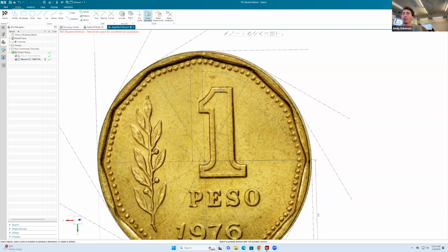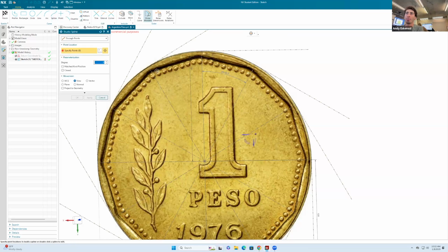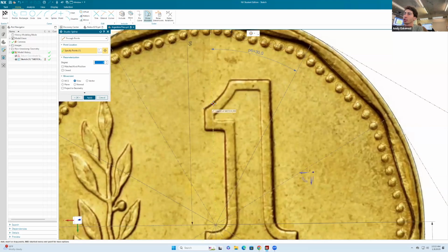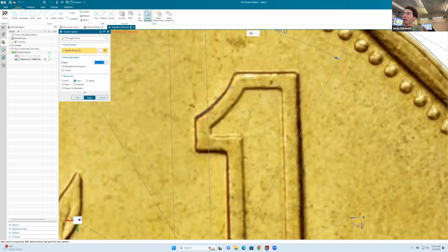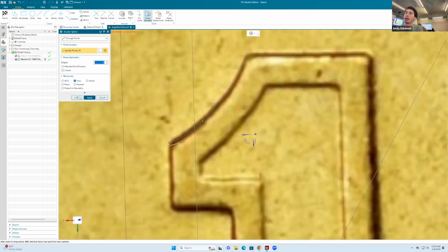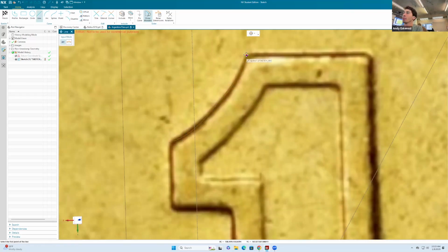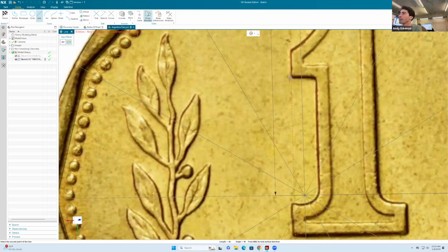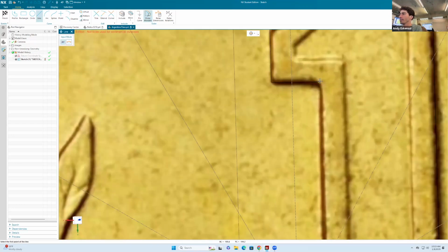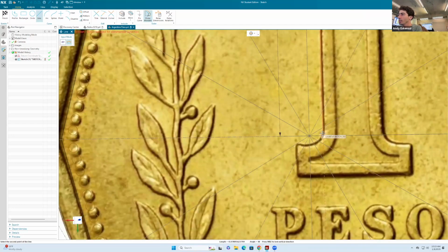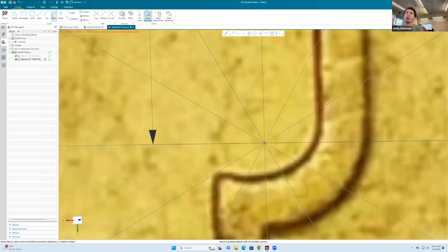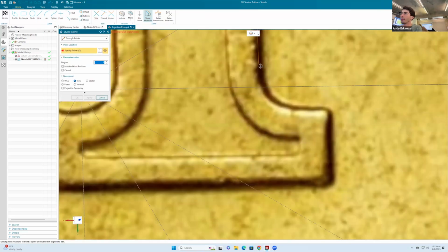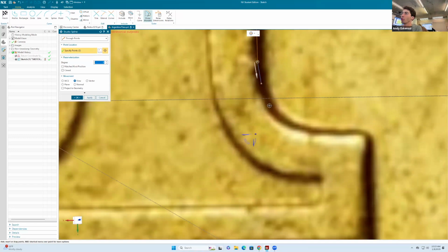But now, maybe this is the one that we could do together. We're gonna start the spline tool. So I'm gonna click here in spline and I'm gonna start tracing out the 1 in here. I'll say, okay. Then I go here with the 1, with the line. I'm gonna go all the way down like this. This is approximate, right? It doesn't need to be perfect. And only trace the exterior, because then we can use the command that we learned last time, which is offset entities, that will allow us to create an exact same copy of this.